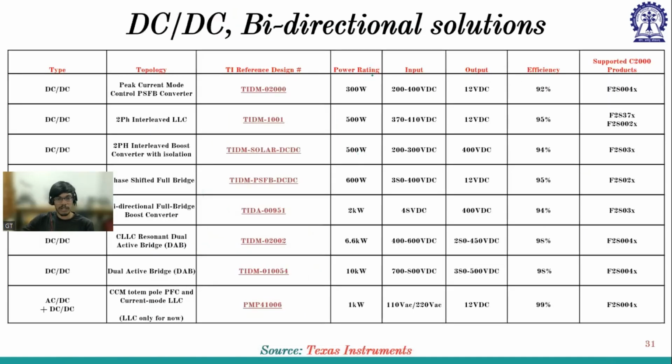And these are some reference designs that are already openly available, and these are the links that they have provided. So for different applications and different topologies, say PSFB, two-phase interleaved LLC, and two-phase interleaved boost converter with isolation. PSFB is the phase shifted full bridge converter. You can click on this link and see what reference design they are offering, whether you can refer to that, whether it will be beneficial, and what type of control techniques they are using. All these things you can see.